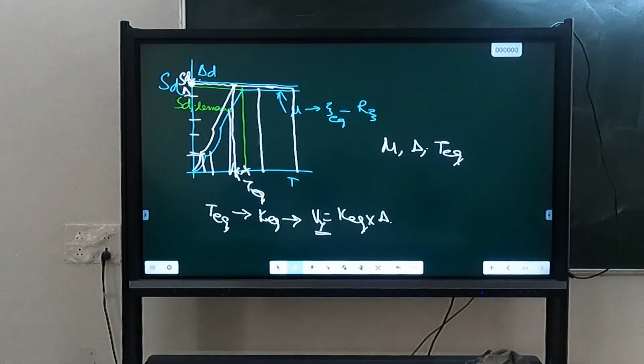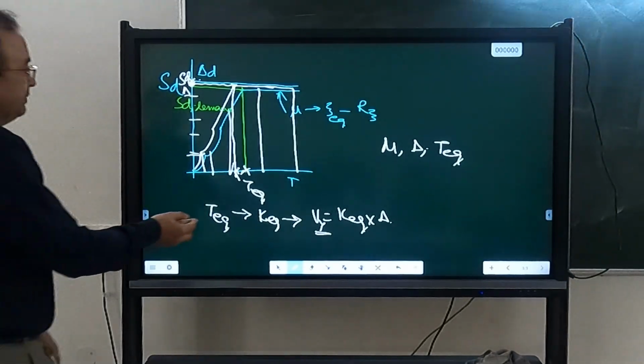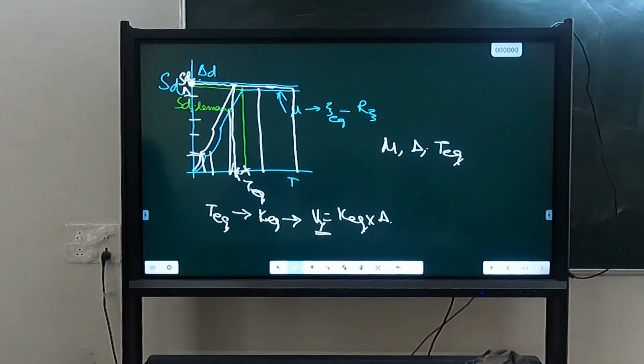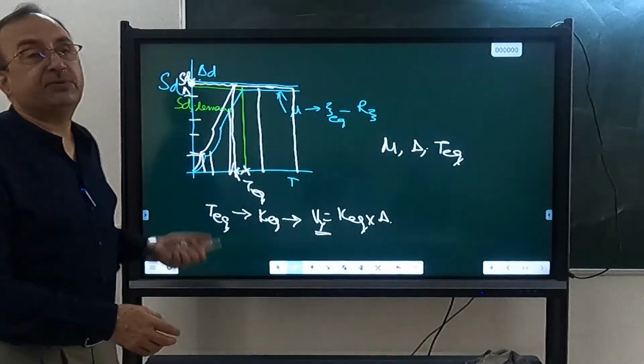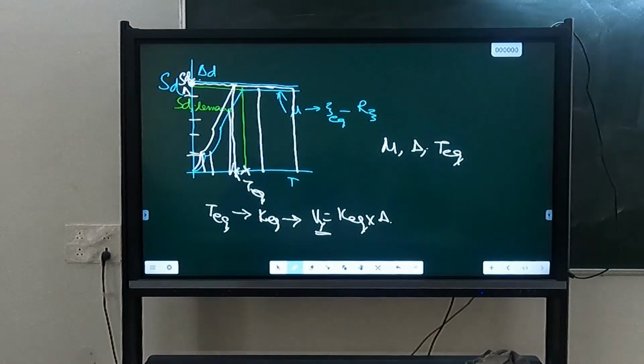So for calculating size and reinforcement both, you need some force, Vy or Vb, for which you should design. So you design for that Vy or Vb, which you are getting from DDVD. That will give you the size and reinforcement. So that gives you an initial configuration of the structure, which you can use for performing pushover analysis to develop the capacity curve. Once that capacity curve is known, then you can confirm its performance. Most probably that performance will satisfy your target performance. If it is not satisfied, you have to do addition.